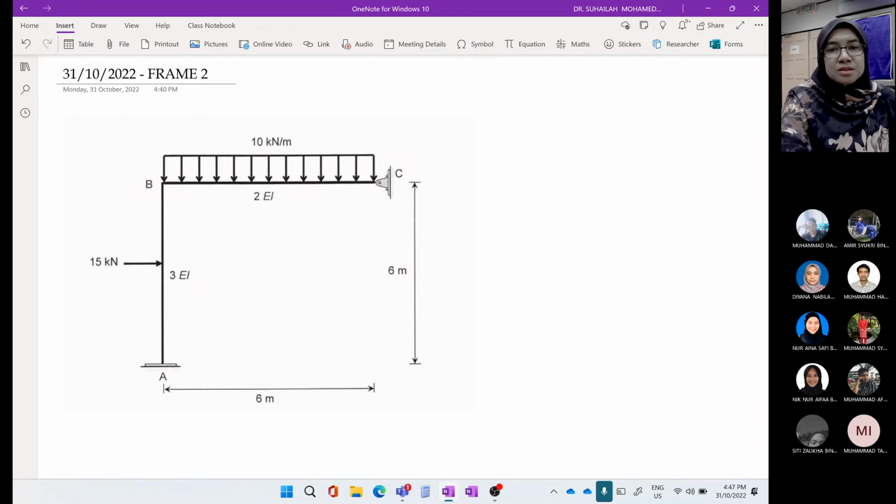As I mentioned previously, in the flexibility method, what is most important is that we know the goal, the final outcome, the objective. The objective is to calculate the reactions. The flexibility method is a method to calculate reactions in an indeterminate structure, and we use it whenever the 3 equilibrium equations are not enough to calculate the reactions, because equilibrium equations can only solve 3.